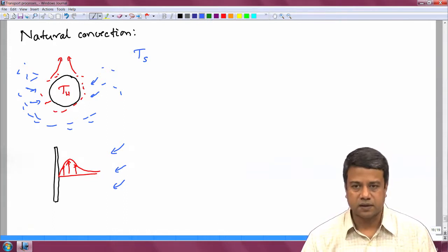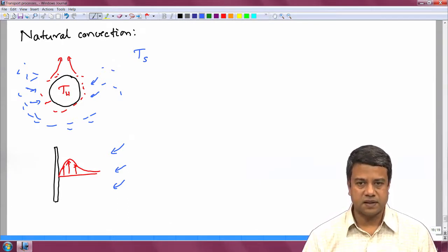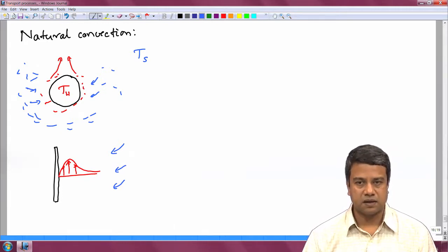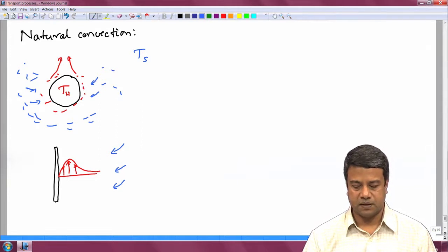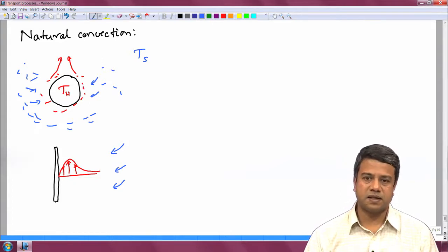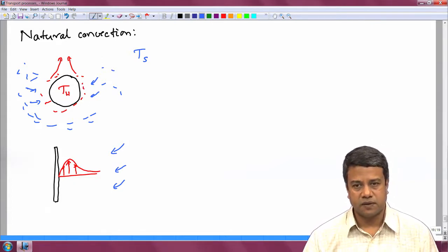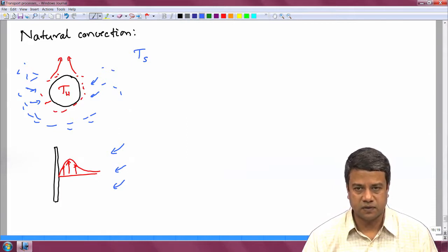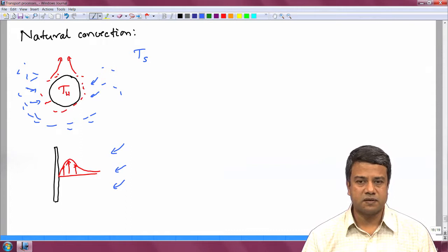Usually, in these free convection, natural convection problems, the length and the velocity scales are sufficiently large that the inertial terms in the momentum conservation equation are higher than the viscous terms. When we do the analysis of natural convection problems, we will come back and see how to scale all of these parameters, but for the moment we will proceed with the assumption that the buoyancy forces are balanced by fluid inertia. So, what is the buoyancy force density due to the temperature difference?